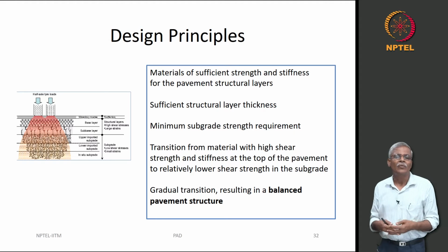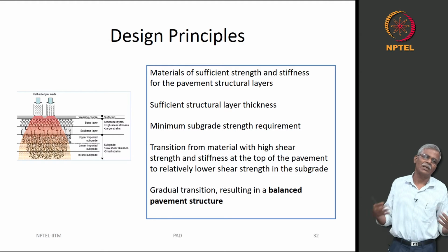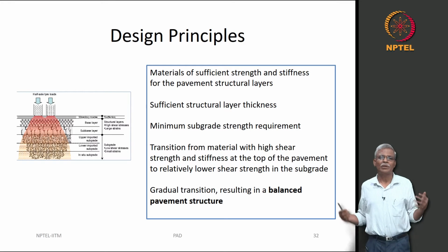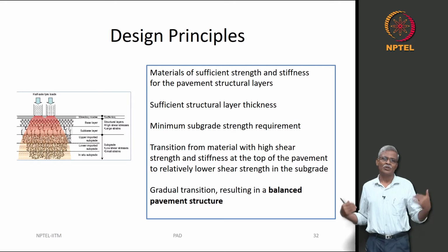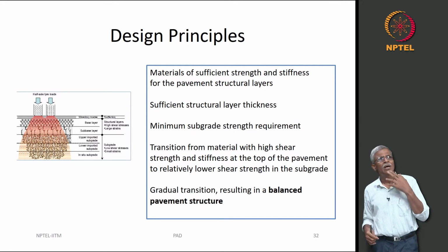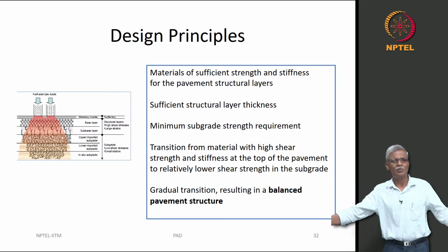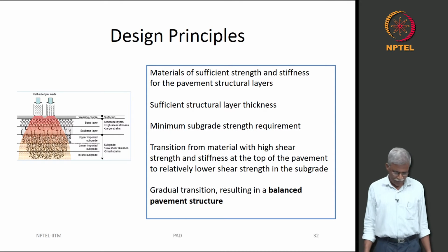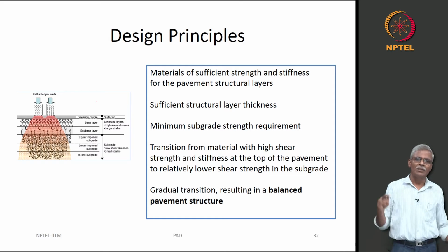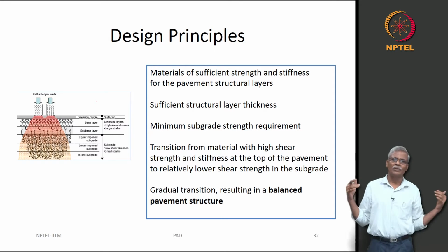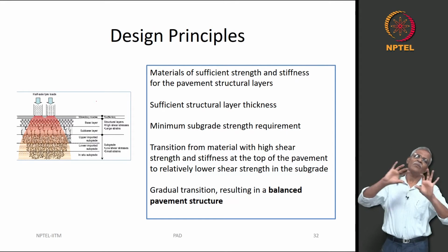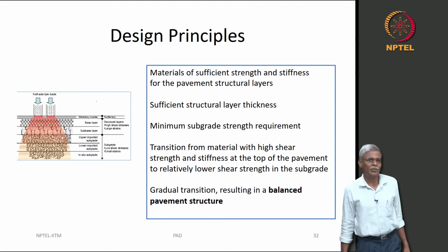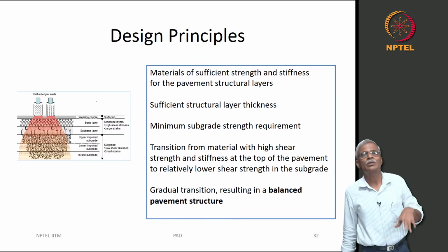See, normally when you are talking about a building structure, building construction, you talk about foundation, basement, superstructure and all those things, and when it comes to pavement, if somebody asks you, okay, where is your superstructure and where is your basement, where is your foundation, you may not really be able to answer. You will say like everything seems to be foundation. No, not really true. So, you can think of the surfacing as something like a superstructure, you can think of the subgrade, or the improved subgrade, more like a foundation, and somewhere in between, the structure could be called something like a basement. Okay. So, they define it in that specific way.